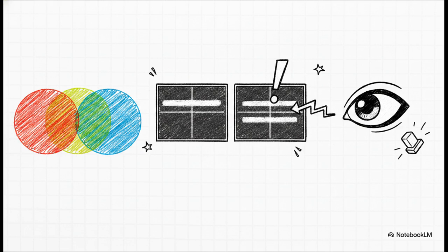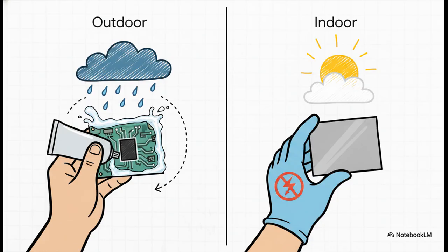If you see 2 lines light up at once, oops, you've accidentally bridged some pins with solder during your IC repair. And always, always look at the module from side angles. Even a perfectly working, newly soldered LED can look like a dead, dark patch if it's tilted even a fraction of a millimeter. And remember, your environment matters immensely. If you're working on an outdoor screen, you must carefully reapply the waterproof, anti-corrosive glue around the board edges. Skipping this step practically guarantees the panel will fail again after the very next rainstorm.